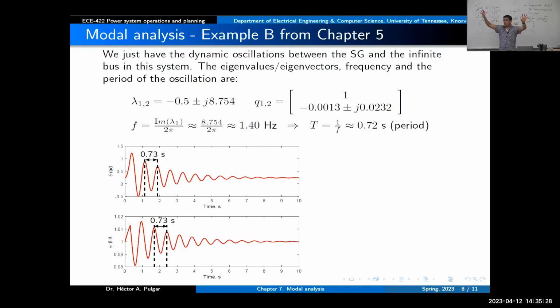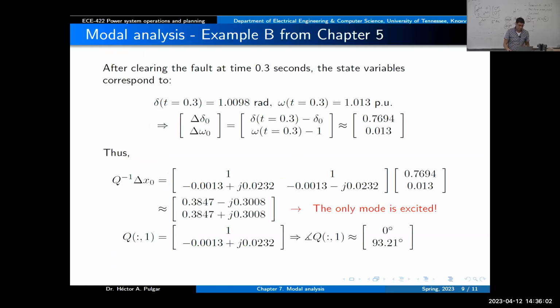But in the other situation, when you have two finite machines and an infinite bus, we calculated 4 eigenvalues related to the motion of the machines, but those are pairs of complex conjugates. So we have actually 2 physical dynamic behaviors: the 2 machines oscillating together with the infinite bus, or the 2 finite machines oscillating against each other. And that's what we got. So there is consistency there.